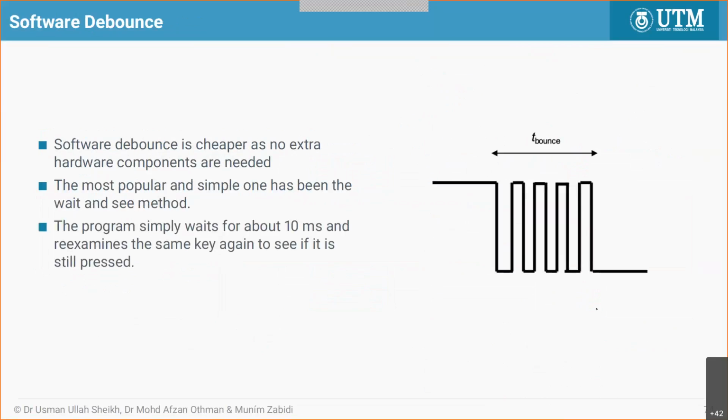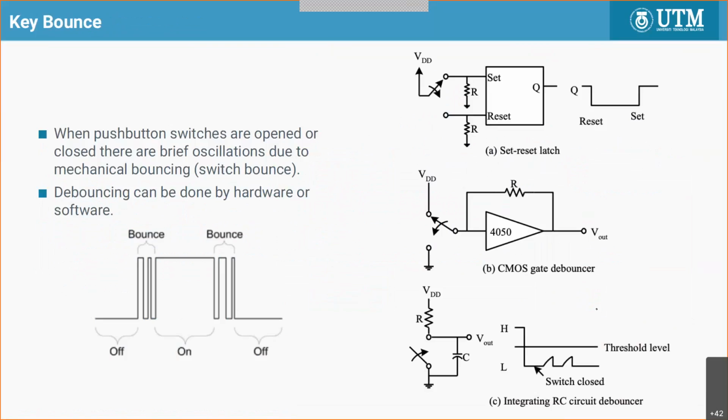And second last slide, key bounce. I have mentioned key bounce just now. On your Nucleo, you have the RC. Of course that one is no problem because there's only one switch, and also people who are first timers to use the Nucleo board don't know about key bounce. They press a button, they expect to have clean output. So of course the board already included the RC there.